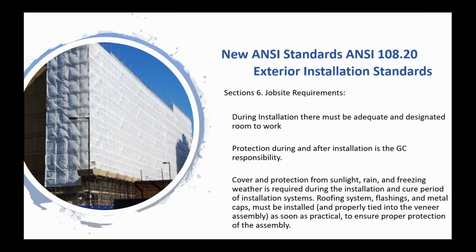During the installation, there should be adequate and designated room to work. That's, again, another gauge porcelain tile statement that you wouldn't typically see in a tile installation standard. But when you're dealing with tiles as large as 5 foot by 10 foot, you can't be expected to do that in a small hallway. Protection during and after the installation is the general contractor's responsibility.